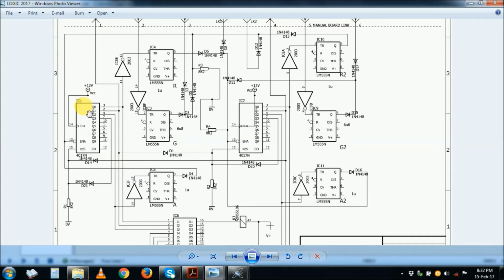So as you can see where you wired, they are wired straight there, so you must connect the relays according to that. Now the timing of the output is determined by that setup here on the capacitor. Remember, the capacitor is responsible for timing, and in the circuit that I've built, we are looking at 1 micro. I'll show you the values of the components around this timing circuit. We'll actually do the timing circuit as well.